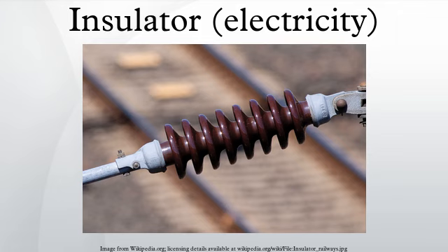Most high-voltage insulators are designed with a lower flashover voltage than puncture voltage, so they flash over before they puncture, to avoid damage. Dirt, pollution, salt, and particularly water on the surface of a high-voltage insulator can create a conductive path across it, causing leakage currents and flashovers. The flashover voltage can be reduced by more than 50% when the insulator is wet. High-voltage insulators for outdoor use are shaped to maximize the length of the leakage path along the surface from one end to the other, called the creepage length, to minimize these leakage currents.